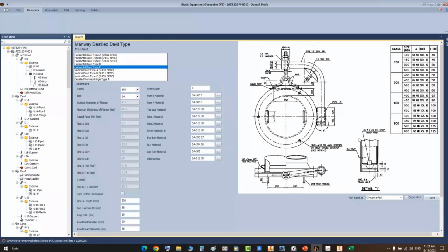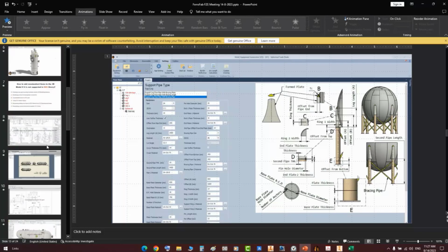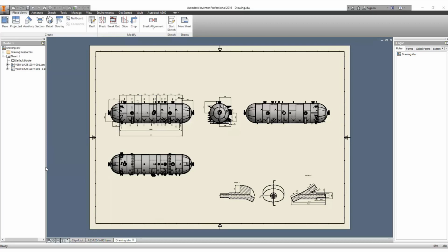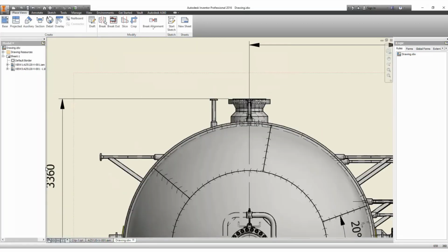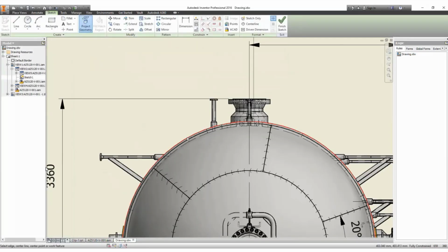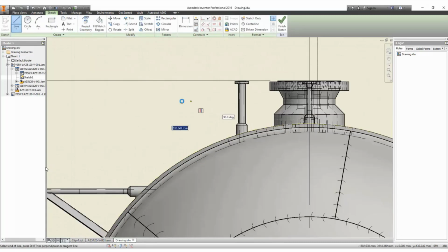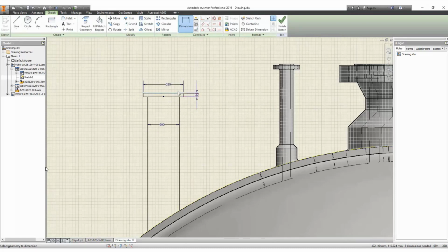That's the first option. The second option, you just make it on the drawing as a 2D drawing. If we come back here, as mentioned, if you would like to add a clip, for example, and you don't need to generate a 3D model and consume time in that, you can just add a view as a 2D sketch on the view, like that. That's another way to do it.